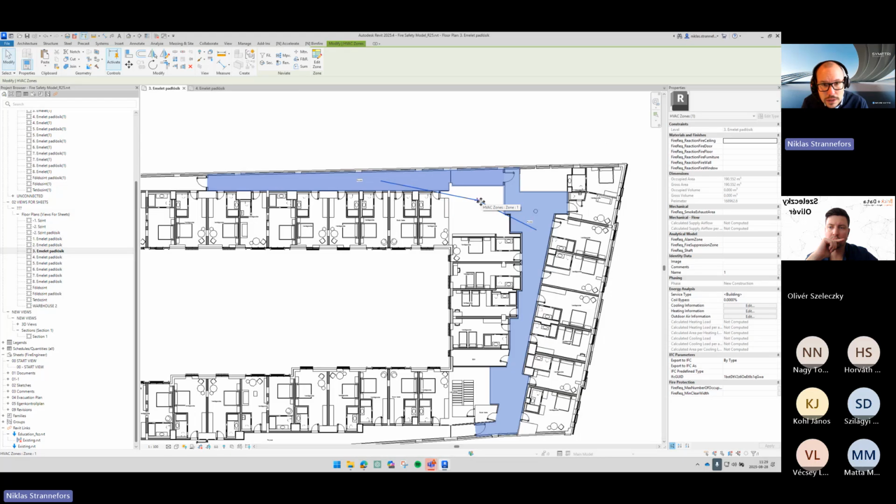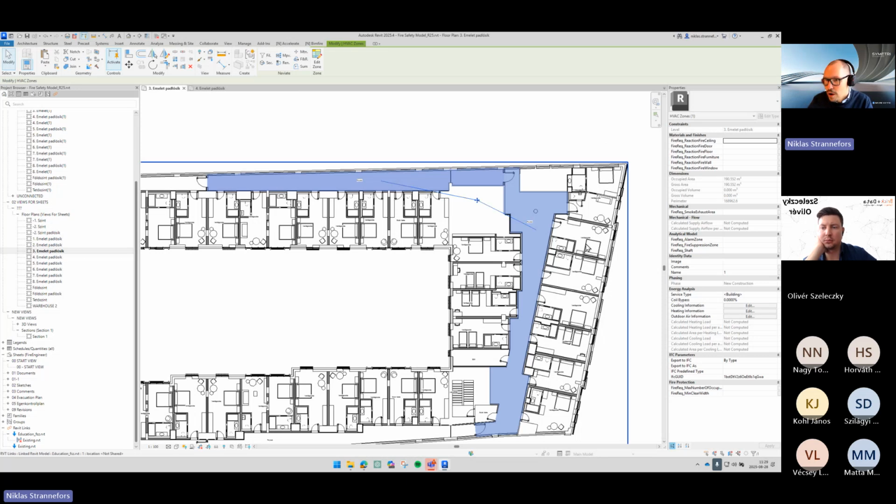Theoretically, you are correct, but Autodesk hate these zones, so they didn't give them any love until 2026, when they actually redid zones. Before 2026, they are super buggy if you want to colorize them. They just stop working. The area is correct, but it sometimes drops some rooms or spaces. It's still part of it, but it doesn't colorize it because of reasons.